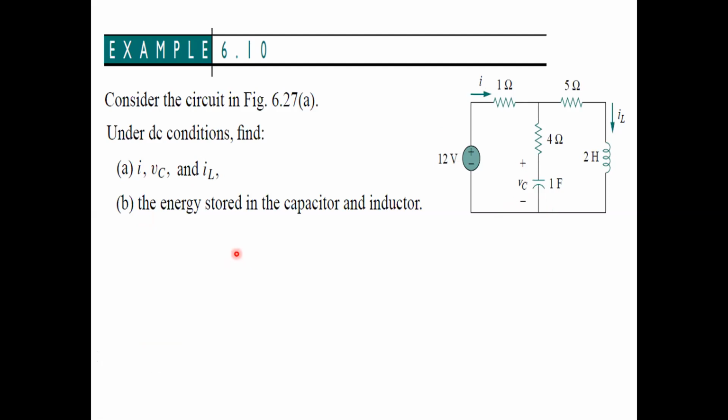And what should be our technique? First of all, note that it is a DC power supply. So capacitor will be open circuit and inductor will be short circuit.